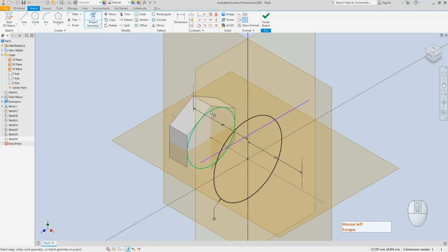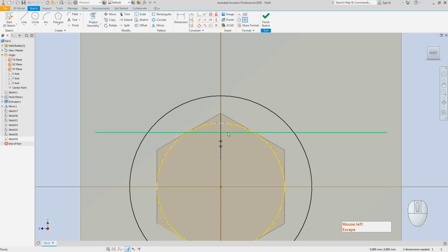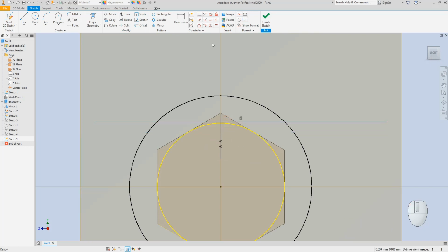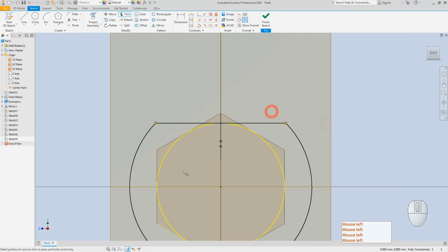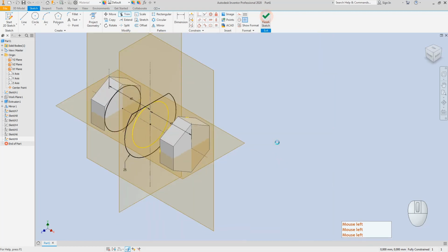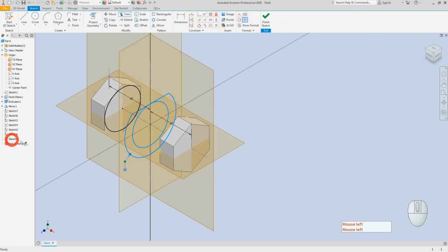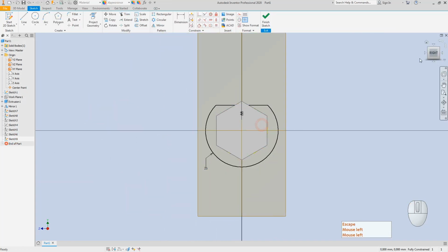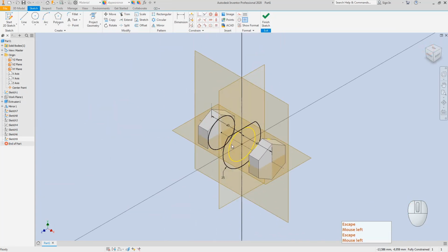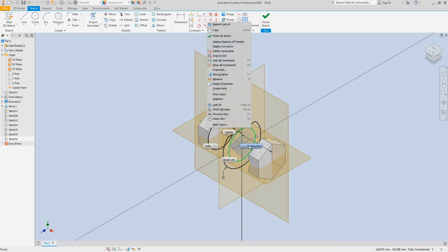For this reason, I project a geometry, as you see, and I would like to have that line at least tangent to this curvature here. I will give the tangent curvature. And from this point, I will make the trims on each side, like this. We have 3 profiles, and let's make this profile inside a clear.